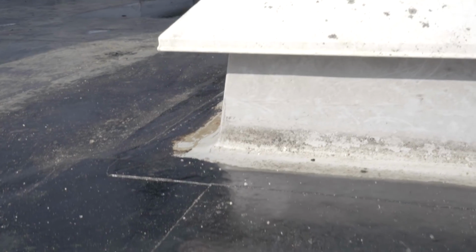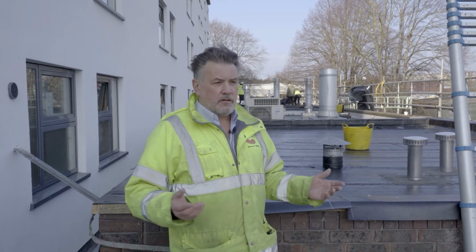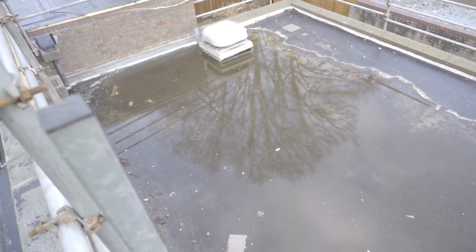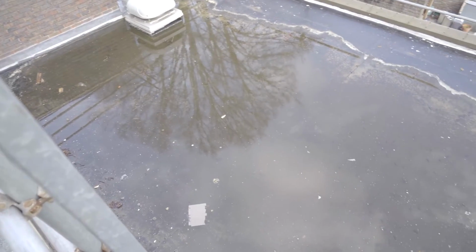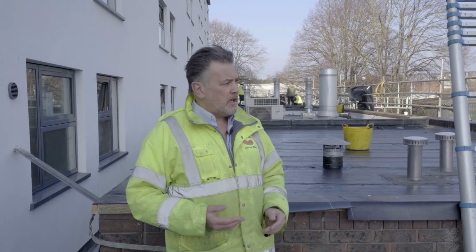I've got to look at the skylights. I can see just from a visual inspection that they're not very good quality. With all our components, we'd like to put them back with items that have a lifespan at least equal to the roof that we're going to put down. I can see, first of all, that there are outlets that are too high. They won't be helping with the ponding water. So I know we need to reduce those outlets in height.